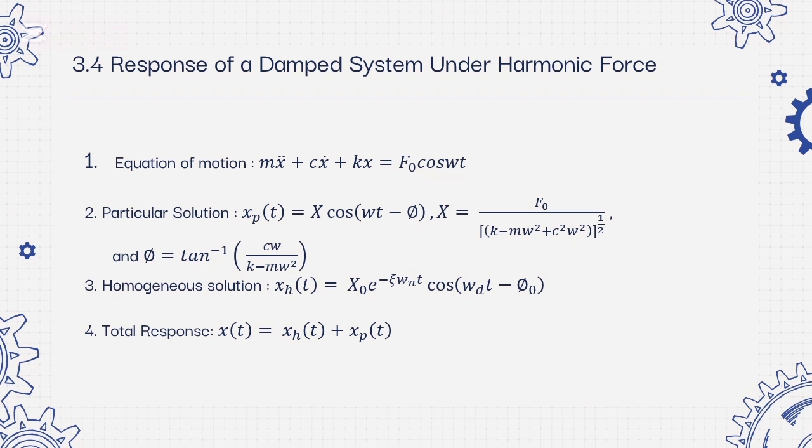There are a lot of examples in our life of damped systems under harmonic force. For example, car suspensions use damping to respond to road vibration. Similarly, skyscrapers employ tuned mass dampers to counteract wind-induced oscillations. That's why we should always design the damping system with zeta and natural frequency to keep the frequency ratio, r, away from the critical ranges, so we can avoid resonance.